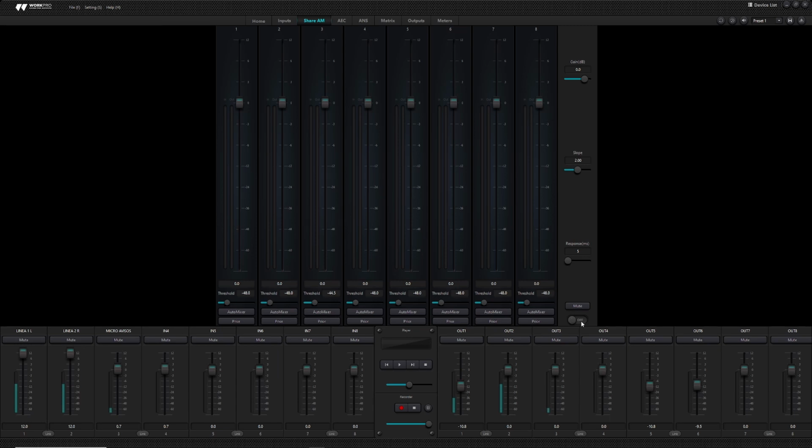First of all, we connect it. For the moment, it wouldn't be working because we are not sending the channel signals. We would select the two line signals and the microphone, and we can establish which of our inputs takes priority over the others. In this case, we prioritize the microphone, and we see that when speaking through it, the other signals are attenuated.